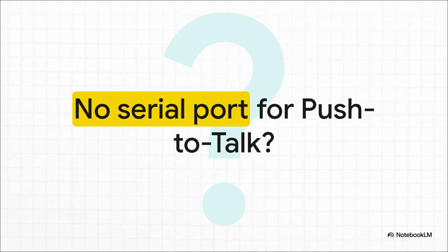Of course, receiving is really only half the battle, right? To transmit, your computer needs to tell the radio to key up. That is usually done via a push-to-talk, or PTT, signal. Traditionally, this was triggered using specific pins on a serial port. But if you're looking at the back of your modern PC right now, you might be a little intimidated if you don't see a standard RS-232 serial port anywhere in sight.